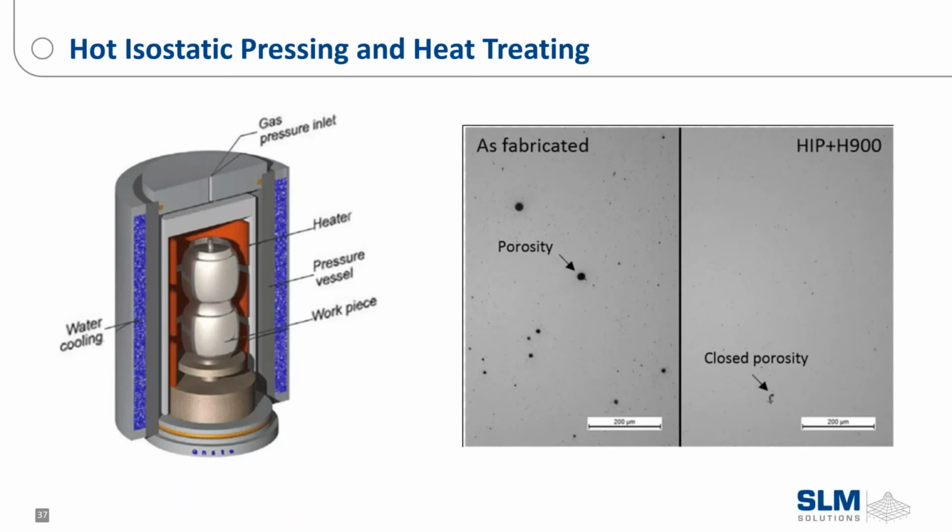Stress relief. I'm going to need a little bit of this once I'm done with this presentation. We have an argon furnace here on the left-hand side and a vacuum furnace on the right-hand side. Argon blanketed furnaces are great for stress relief and heat treat for most common materials: steels, Inconels, aluminum. When we move into aerospace spec work or titanium or Inconels where oxygen inclusion is a major concern, we move into a vacuum furnace.